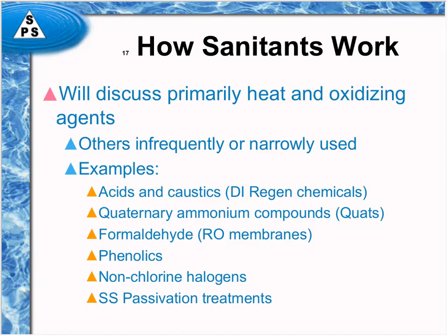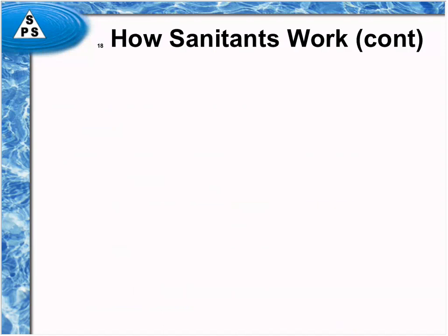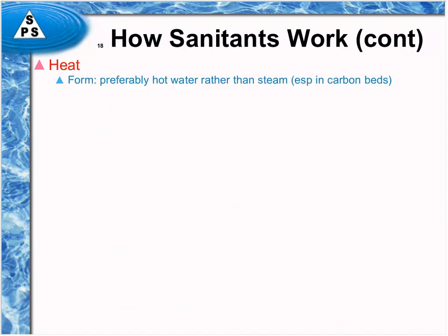And so if you do a full stainless steel passivation treatment, it's usually pretty good at also sanitizing the system at the same time, as long as you don't recontaminate it with nasty water when you purge out the sanitizing chemicals, which is often, ironically, the case. People use city water or something like that to clean out a sanitizing agent, because they just don't have a stored amount of pure water to do the rinsing with. Anyway, let's get into heat.